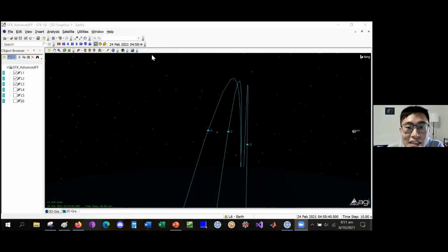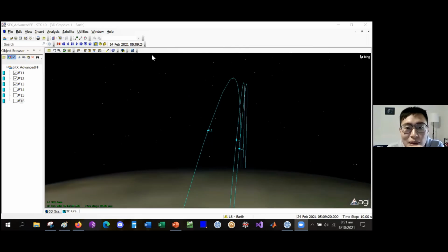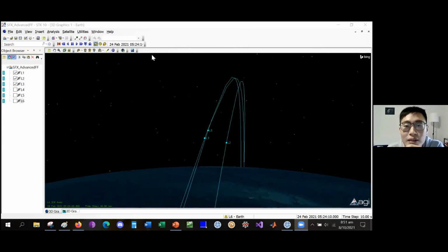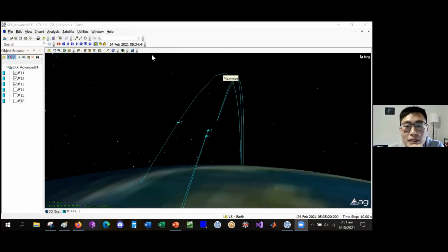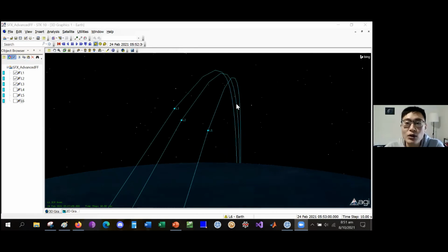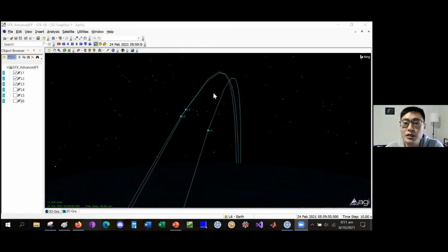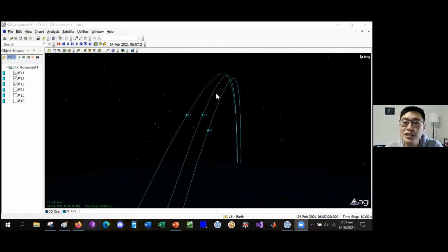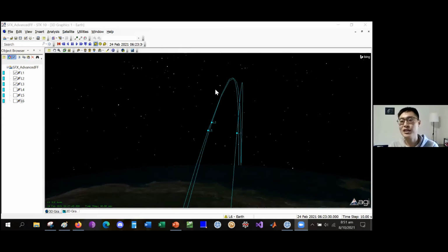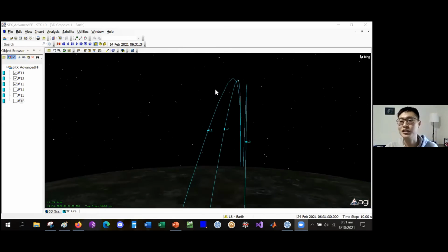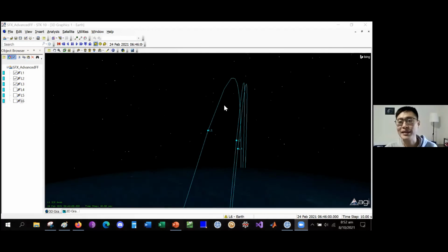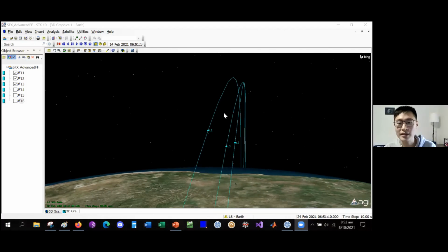Okay, I think I have a question. If we have to launch a couple of satellites at the same time, we want them to follow the same line, how will we make sure they don't get deviated away? So orbit maintenance is a very crucial part of research also. There's always optimal ways to prevent perturbation. Once you have a trajectory in mind, you want to make sure you stick to that trajectory, and perturbations are always just kind of pulling you away from that trajectory. So you need to design an orbit maintenance scheme to do that.